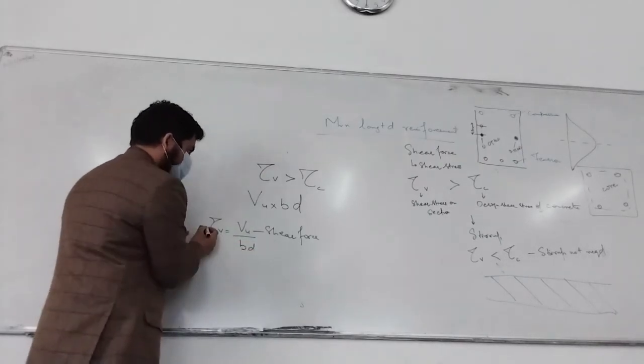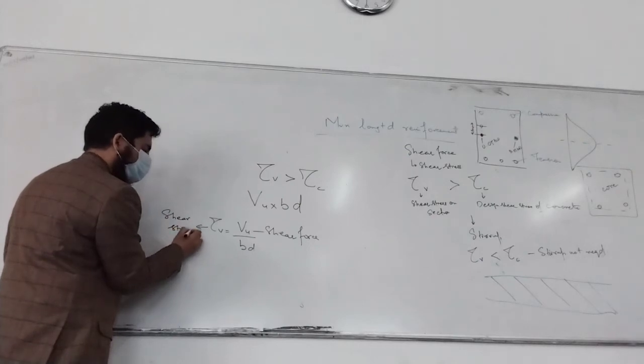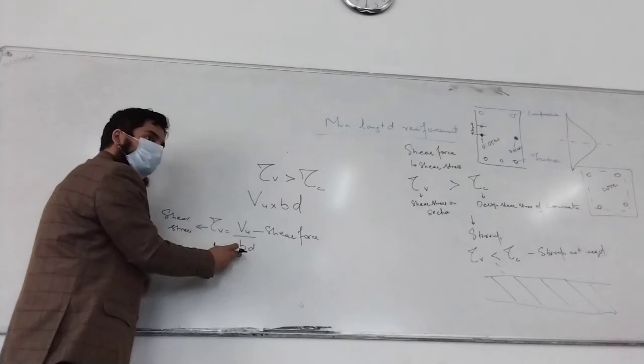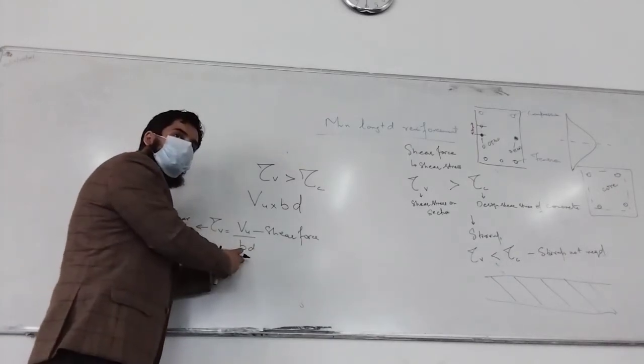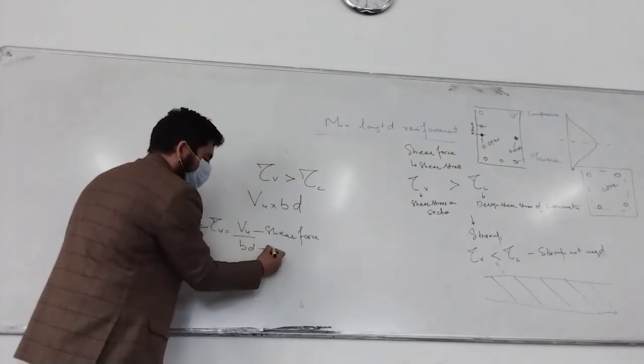Shear stress, this is shear stress. Stress is always equal to force by area. This is force, shear force by area. The effective area is b d. Overall area is b into capital D. So this is effective area.